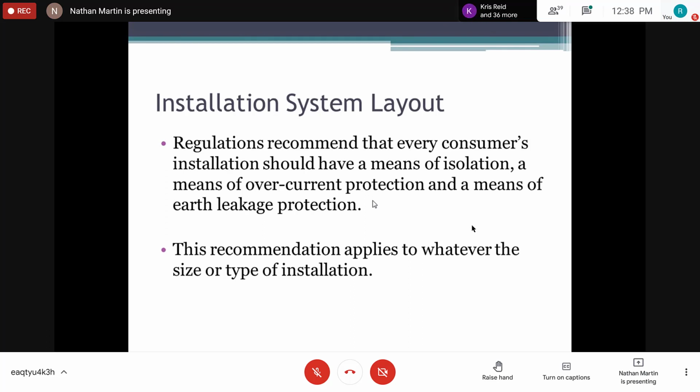Meaning that when you go to the store to purchase it and you ask for a plus main, you will tell them the size main, right? So we're talking probably a 200 amp breaker will come in the panel and is already connected to the bus bar, right? All you would need to do now is actually buy your power line breakers.